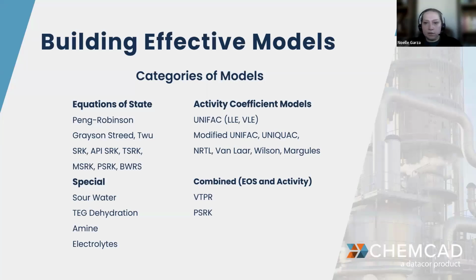So think about the high pressures, high temperatures, non-ideal conditions, polar components, things like that, because some of these models lose accuracy at very high pressures. We can make adjustments to these, but choosing the right thermodynamic model is an entirely different webinar. So this is just some background information. Hopefully it's helpful to at least get the wheels turning.